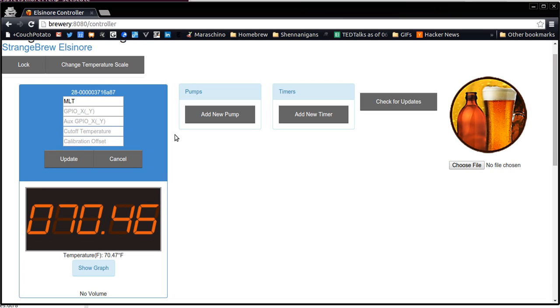And what happens there is that when the temperature probe goes above that value, it will turn off the system entirely. And it will turn off all the GPIO outputs. This is a safety feature so that it doesn't blow up. I have had fire happen from an SSR shorting, and I've got a little bit cautious as a result.